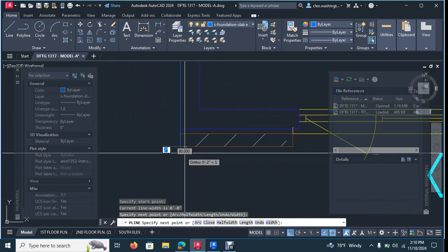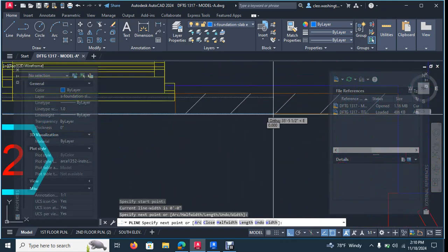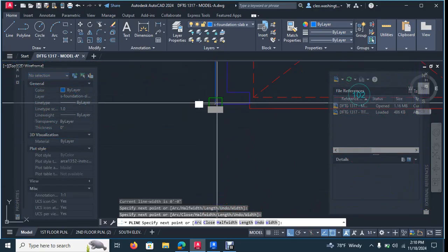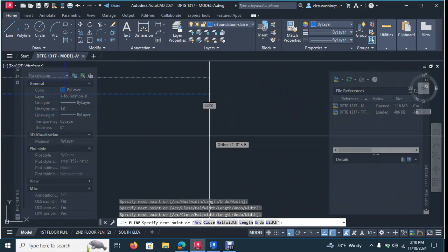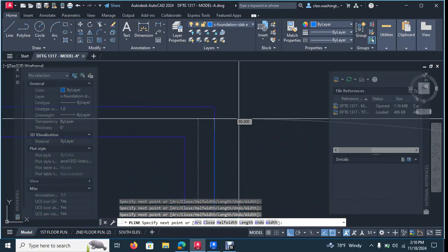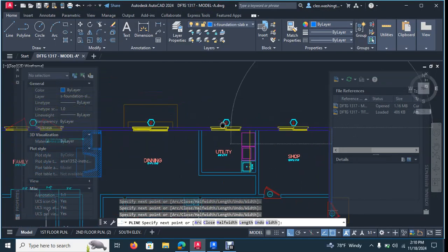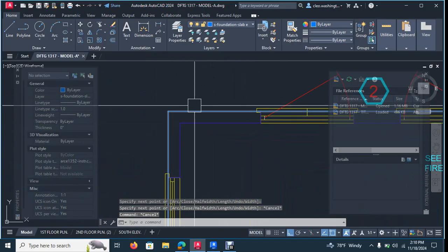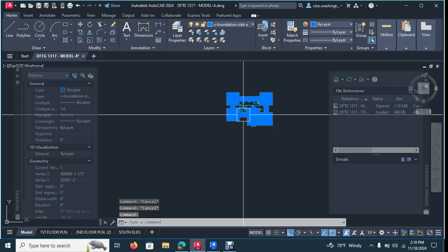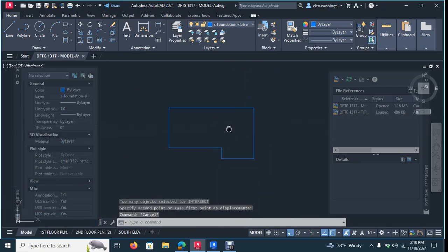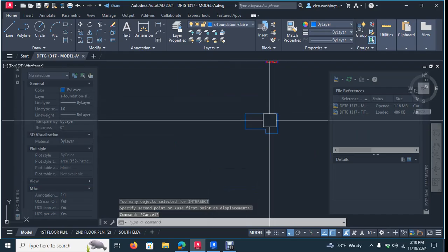slab. This is our brick ledge that we talked about a few minutes ago. And this is what you're going to use to actually draw your slab, right? So you click here. You want to click here. And then you want to click right here. Okay. Now take this guy. Let's move it down. All right. So there's your footprint. Okay.